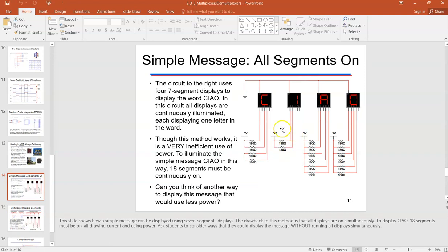Okay, so we did learn about these 7-segment displays, and here we've got a common cathode connected to ground at the top, and then all these pins are connected to power, or VCC. They basically just left the pins disconnected if we didn't want to light up those LEDs, and they've permanently decided what letter is going to show up. So you think of a sign that's just going to say, you know, welcome or something. We're not going to have it change. This is just a way to preset exactly what's going to show up. Okay, real simple.